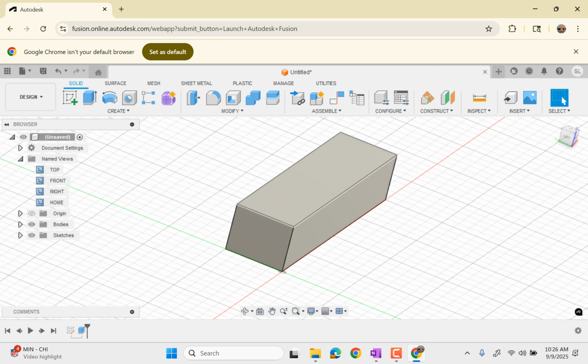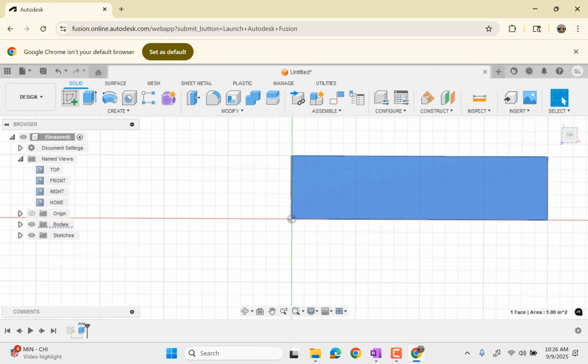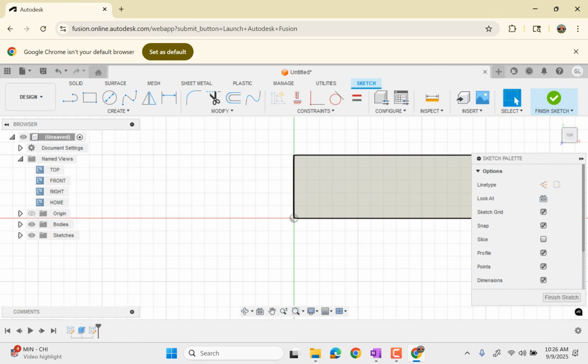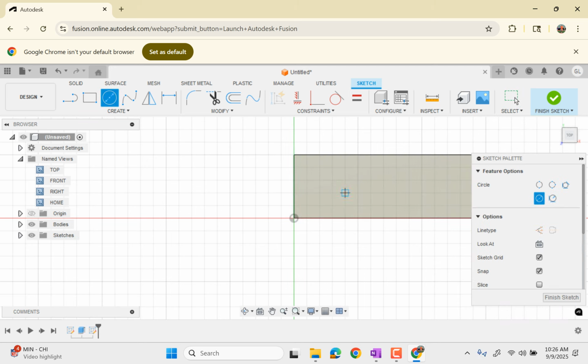But this time, instead of extruding all 4 of them, I'm just going to do the one, and then we'll use the pattern tool. So I'm going to choose this surface, the top surface here, as the one that I'm going to make my hole in. And I'm going to choose that and then say I want to sketch. And when you hit sketch, once it knows what the surface is that you want to sketch on, it'll pop you into position like this. And there's my circle.